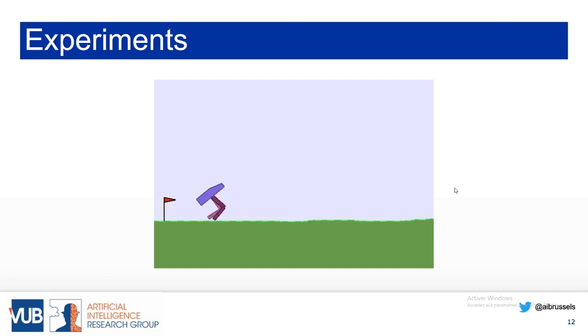And so for experiments, because it's a work in progress paper, so basically the algorithm is somewhat done, but the experiments are quite preliminary because it's an algorithm that takes from this January. So it's only one environment, and it's bipedal walker, so available in the gym, and it's basically a sort of 2D robot that has to walk. It observes a few LiDAR readings of the shape of the ground, and it has an action that has 4 dimensions. It's basically the torque of the 2 hip joints and then the 2 knee joints of that robot.